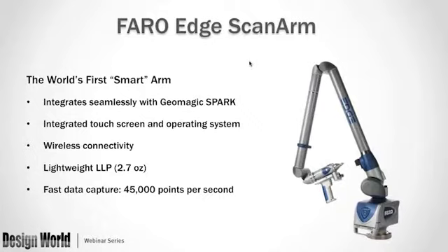It's very lightweight, and its low form factor allows obstruction and collision-free measurements to be taken with the contact probe or the laser line probe, and switching between the two is absolutely seamless. The fast data capture rate for point cloud is 45,000 points a second.